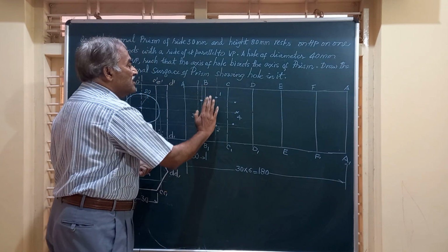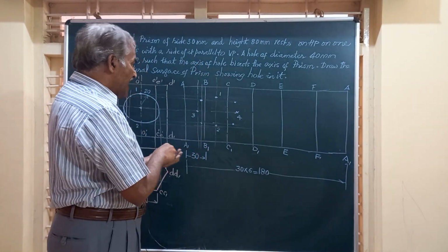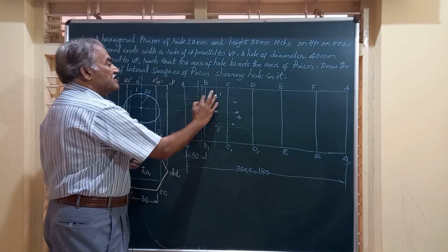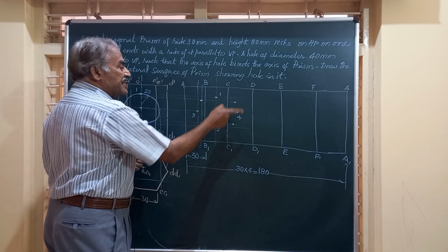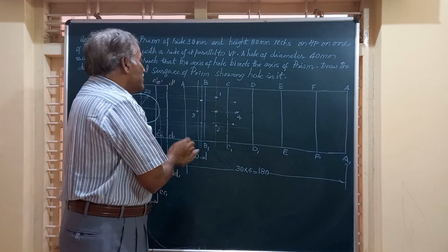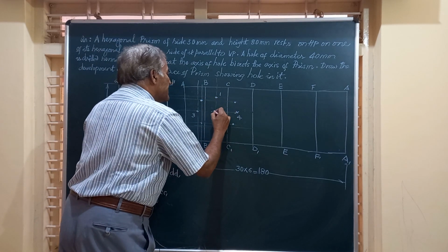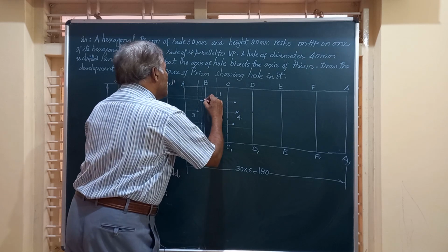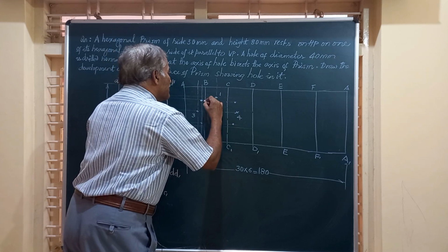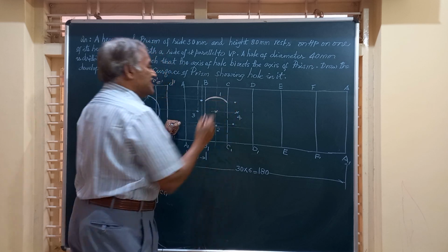BCC1B1 is parallel to VP. And here this is the center of the ellipse. Since this distance is the radius, since it is on a flat surface, you are going to get an exact circle here. That is to say, you can join these points by a smooth curve from the BB line to the CC line. These are the points. So you can take a compass and draw an arc like this.